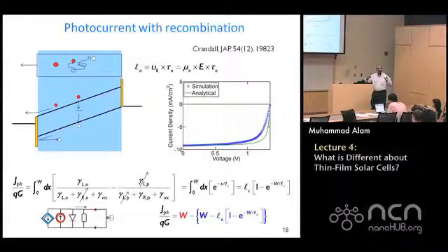Independent, because if I could collect everything independent of voltage, that would be the thing. But of course, this blue one is telling me what fraction of it is recombining inside the device before getting out. And so therefore, this whole quantity is essentially this voltage-dependent current source. Again, in the presence of recombination in this region, the current will be voltage dependent.